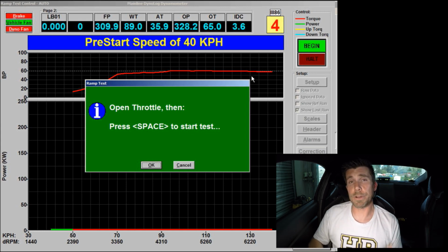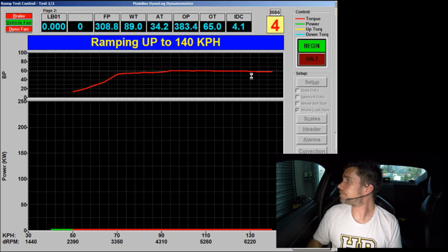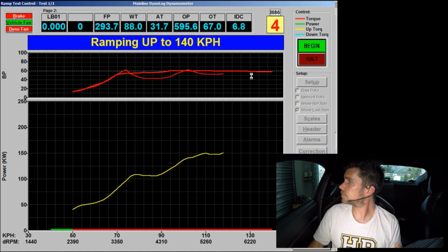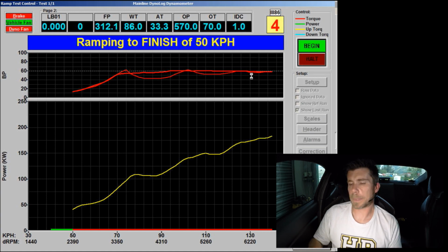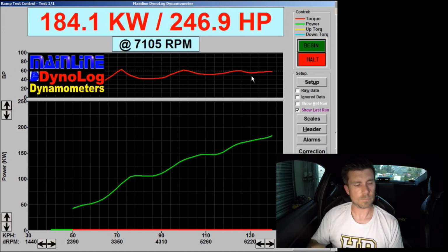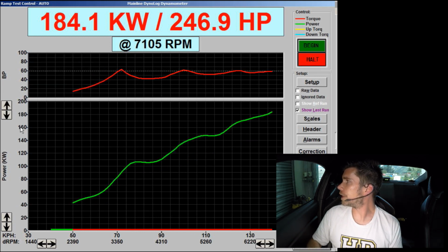Alright, so we're ready for our second run. Let's do that now. Okay, so we can see this time our proportional gain alone hasn't given us particularly good boost control, and what we've got is this situation where our boost control has oscillated.